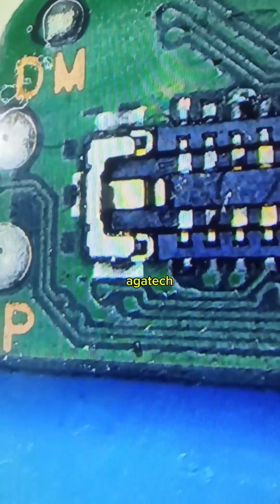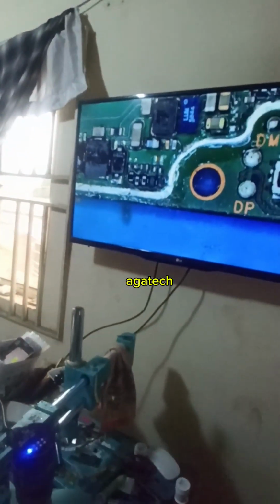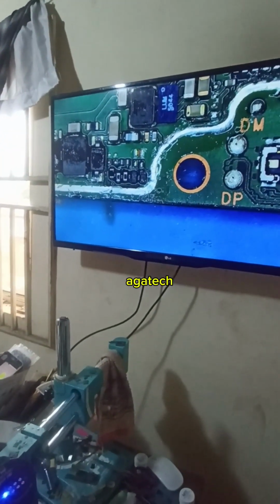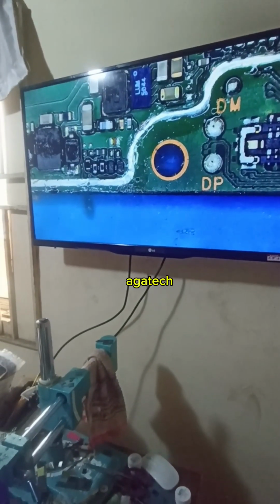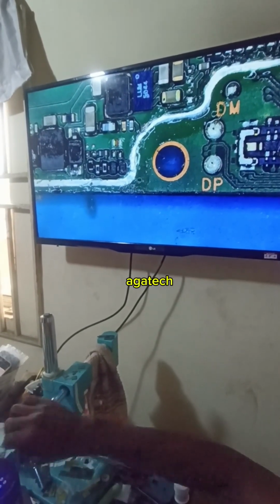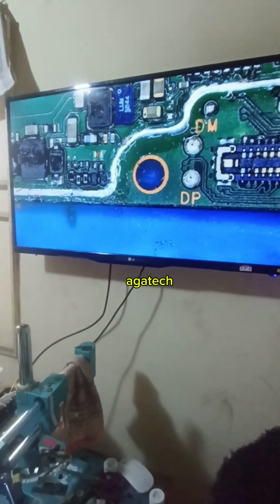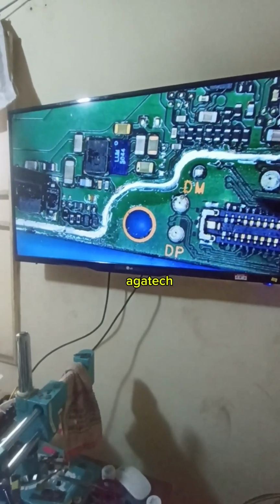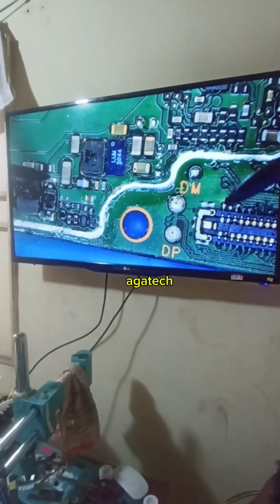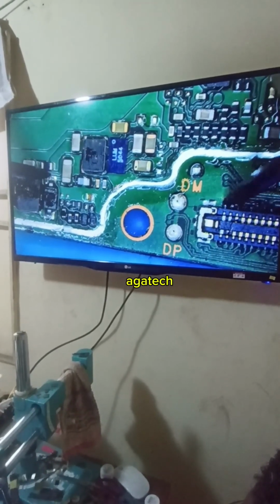So what did I notice? Let me show you. Let's see it together. I set my meter to continuity, and I decided to check if the two points are connected. So from this diode, that signal is supposed to come to this first leg of the screen connector, and it's supposed to beep because the meter is in continuity.